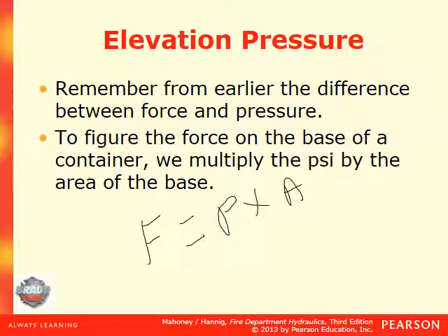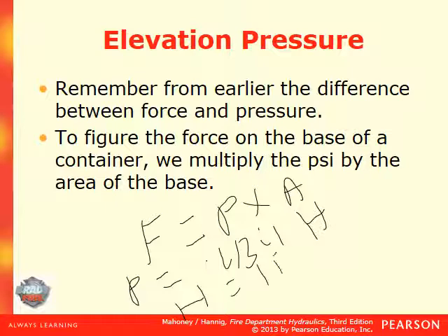Pressure is going to equal, so you got to do a little algebra here, 0.434 times the height. And height, of course, will always be in feet. And the area is done in square inches. So basically that's 12 times 12, depending on the size of the container.